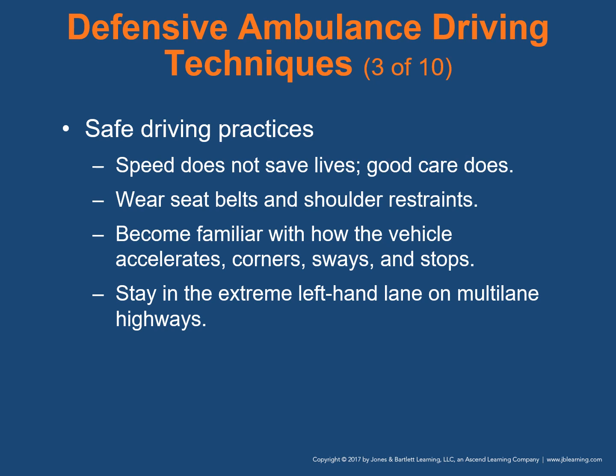Become familiar with how your emergency vehicle accelerates, corners, sways, and stops under various conditions. Make sure you understand the vehicle's braking characteristics and the best downshifting techniques. On a multi-lane highway, stay in the extreme left-hand or fast lane, allowing other motorists to move over to the right lane when they see or hear you approach.